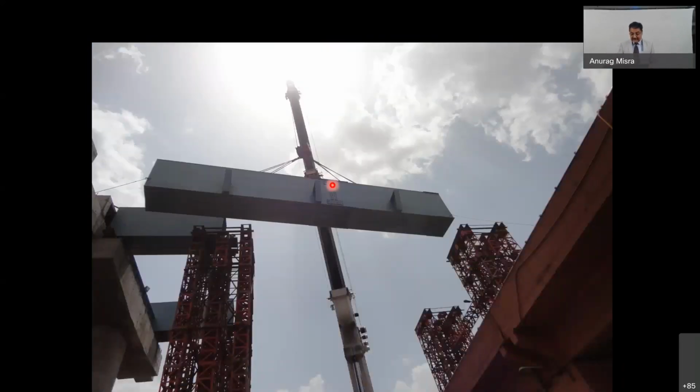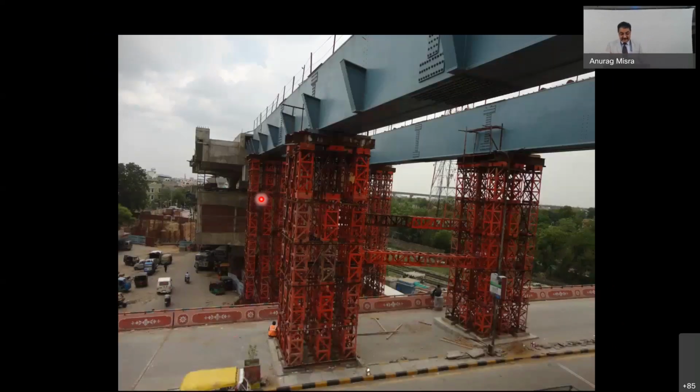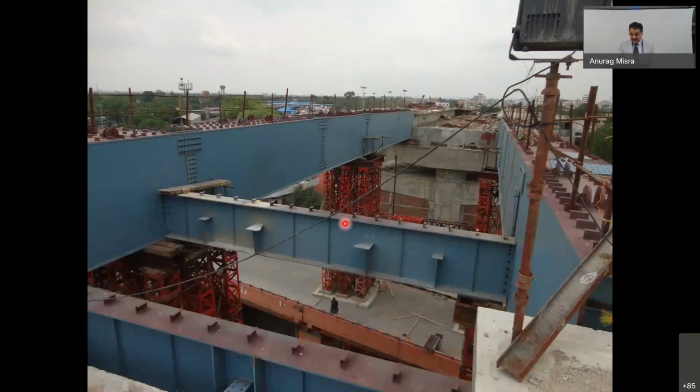So you can see that these are the box girders. So two main box girders, and they are made in pieces which you can erect and assemble at site. You can see there are certain splicing joints here. So after making these joints into one piece, you just erect them, and then these cross beams, etc., are done simultaneously later on.